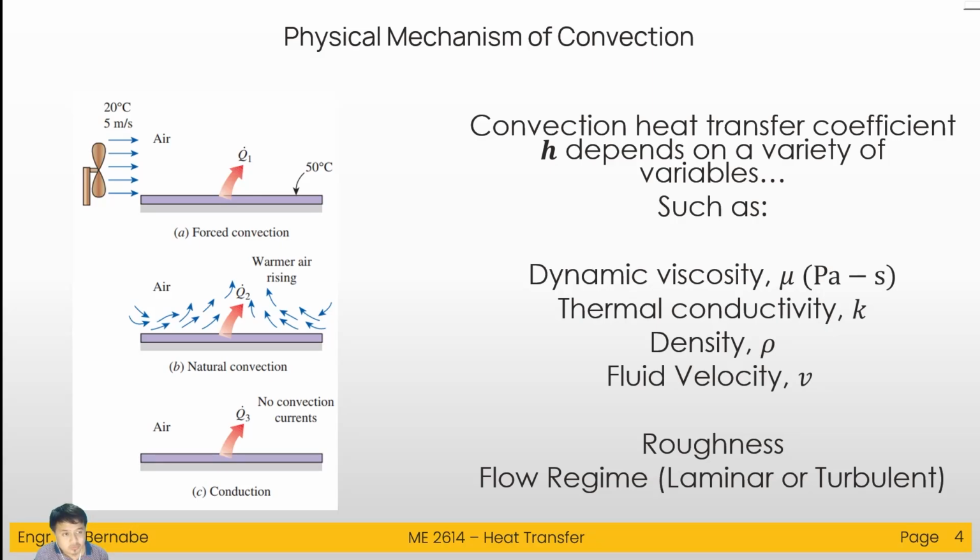Without the electric fan, you will only feel natural convection, or in a very simple example, it could be just conduction and radiation. But you know that if the electric fan is pretty high in its setting, you will feel a lot cooler. But the reality is the temperature of the air is just constant. If you can imagine, it's just 25, but it's moving towards you. That is why it feels colder. So convection is the same thing. The fluid velocity highly affects this h, which increases the convection, which increases the heat loss that you feel.